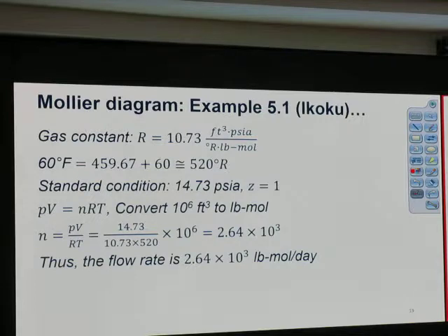Make sense? Because if the temperature goes up, the required cooling will equal the change in enthalpy, which is mCp delta T: mass flow rate multiplied by the difference in temperature.